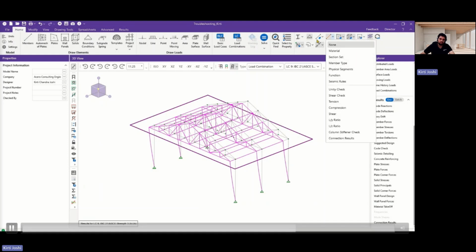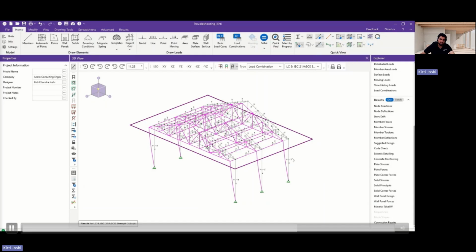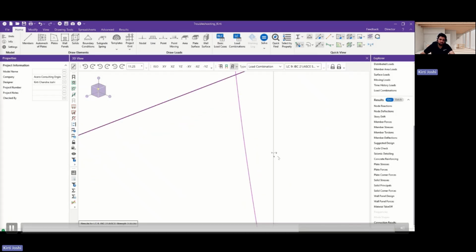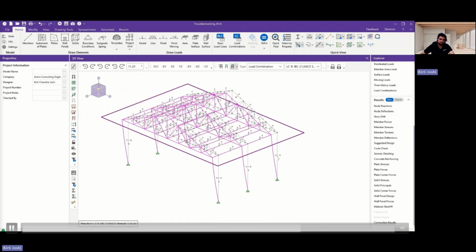So this is the way I can also see the deflected shape, because once I run the model, the first step is to check the deflected shape. I mostly use that. You can also display your y-axis. We can also see the deflections in tabular form. You have the results tab options, and you have the node deflection option.